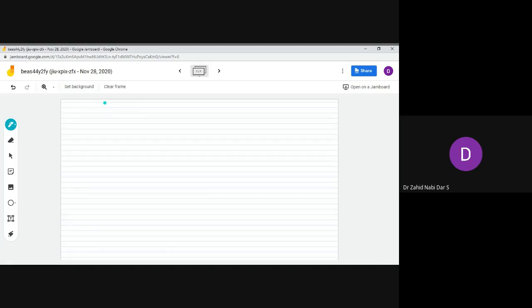Now, as far as the total number of stator conductors is concerned, the number of turns per phase we saw over there was 341. But the turns per phase should always be an even number, so we will take the next even number, because the turns per phase cannot be odd. We cannot have a fractional turn, it has to be a full turn. So it has to be this.